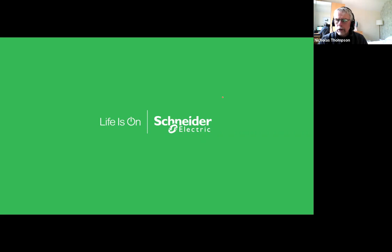Right, the fault levels are reducing in the networks due to displacement of conventional generation. What solution is there for reliability of current-based protection systems for 100% or near 100% renewable-based generation? Wow, right, that's a challenge, because when you say fault levels are reducing in the networks, it depends on who you talk to. The DNOs do experience grid substations tripping because of the contribution of power from renewables. WPD have had issues in the past with solar farms tripping the grid substation. So it is a problem for the DNOs.